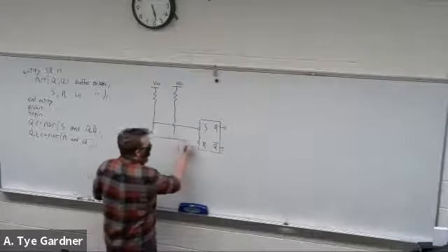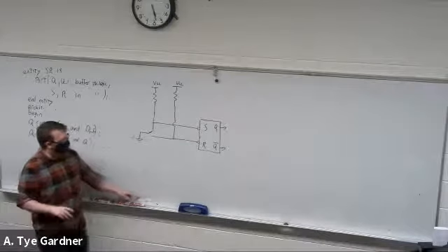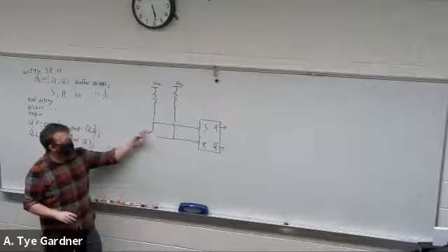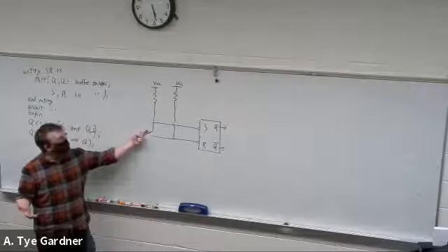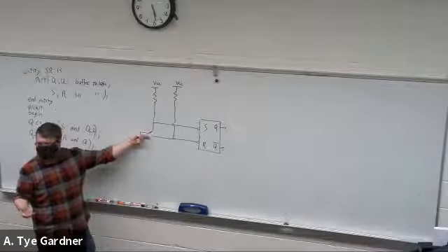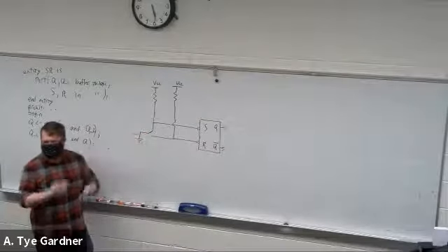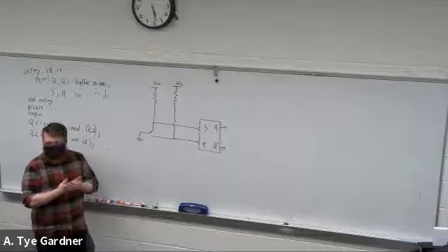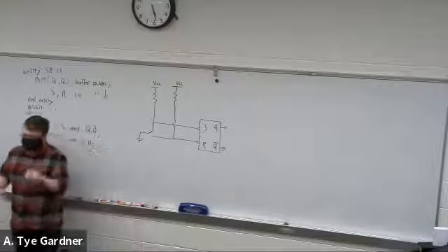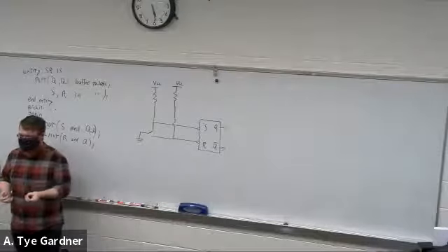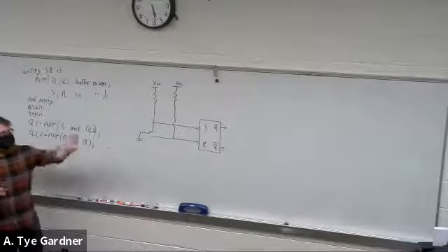And then my switch, when I throw it, look what happens. So let's say I'm on set, so I'm 1. It has that memory, it's holding on. When I throw it to reset and it bounces, what does it do? It goes reset, reset, reset. So it's 1 and then it goes 0, 0, 0, 0. Well, it doesn't matter, right? Because I'm just reasserting the fact that it's 0. That's not an issue. So there's no issue on the bounce.